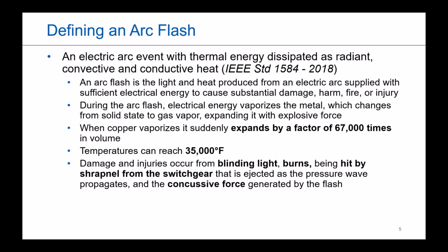And along with all of this, you have what's referred to as the arc blast. This is the pressurized wave that comes out of it. It's generally concussive force, and that concussive force can be strong enough to not only fling a fully grown adult across the room, but it's strong enough that you could potentially even see a collapsed lung.